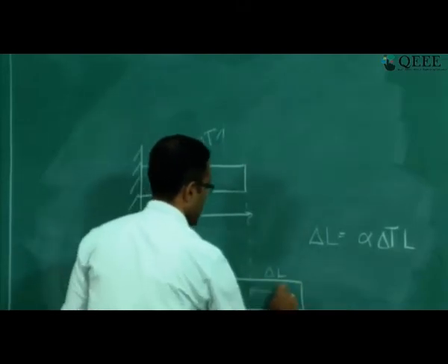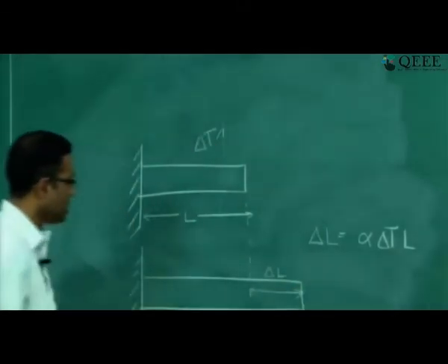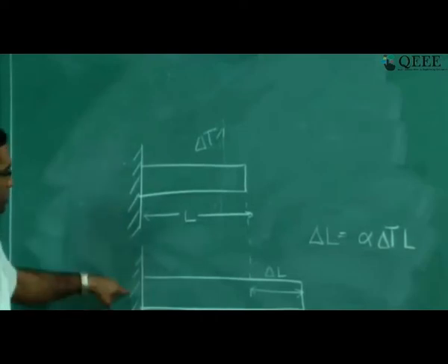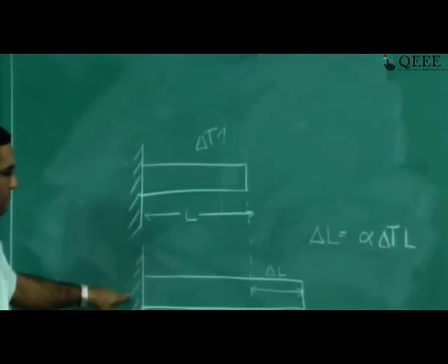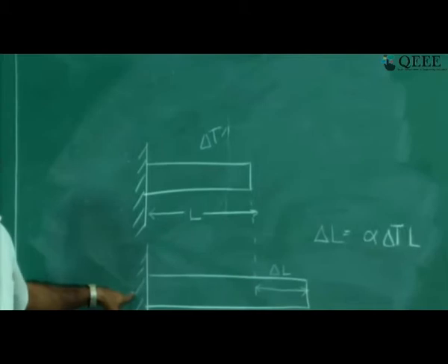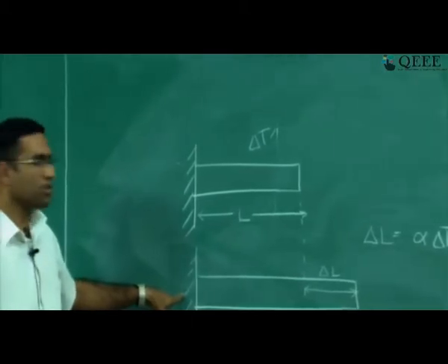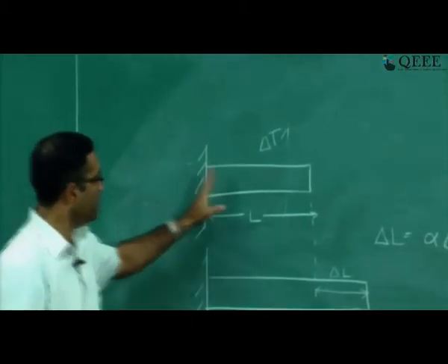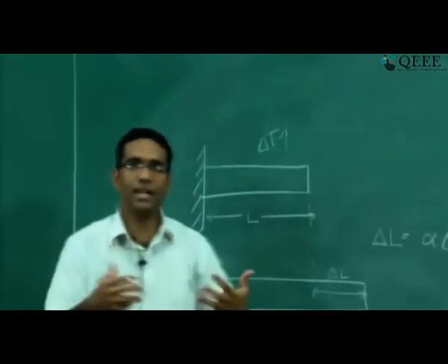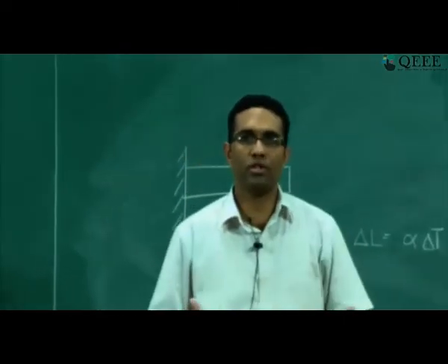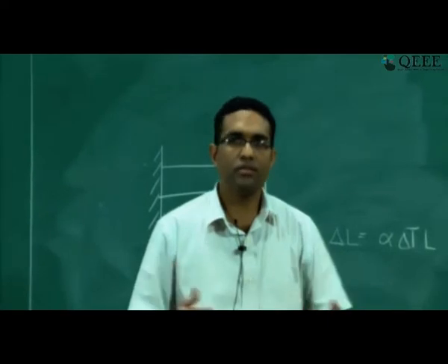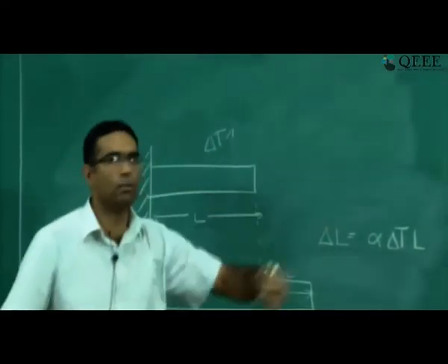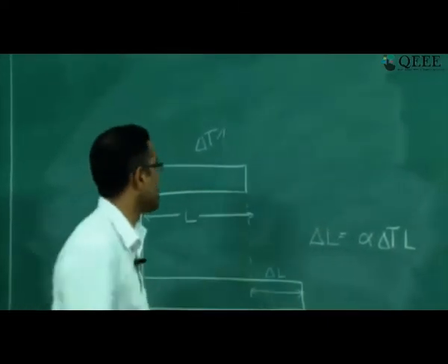Now you need to ask the question: the body is subjected to a change in its length, but does that mean that it is subjected to stress? The answer is no, right? It is free to expand. There is nothing resisting the body's deformation. So essentially no stresses will be induced if you simply heat the bar. It's a very important concept.